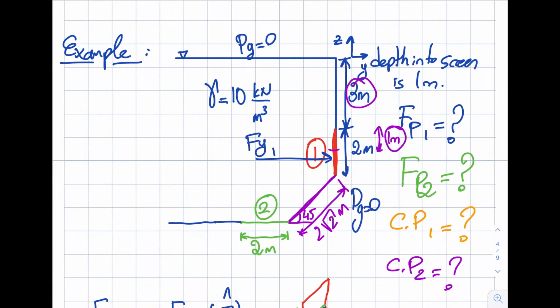There's nothing new in here from that angle. You just calculate the moment with respect to this particular point. You call it O. Let's say that the pressure force is acting here. It will be a little bit below the center. This is the center, so let's say it's acting in here. Then this distance times that force about O will be the moment. The rest is exactly the same as what you've been used to. So there's nothing new in here, in a good way.